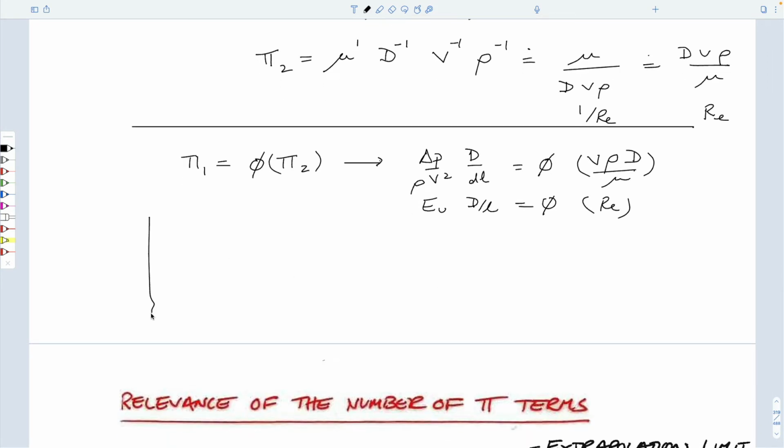And so we could draw this same figure that we had before. That would be Reynolds number versus Euler number. And I'll write these out. So this is delta P over rho v squared. This is v rho d over viscosity.